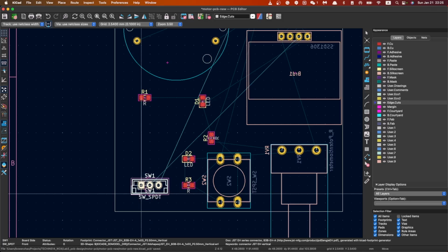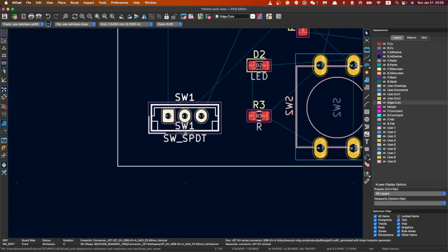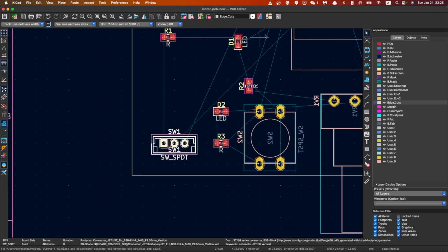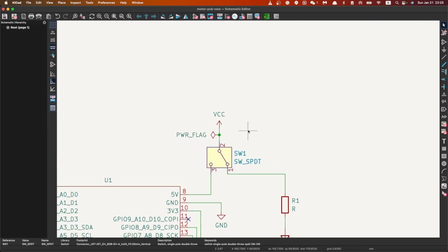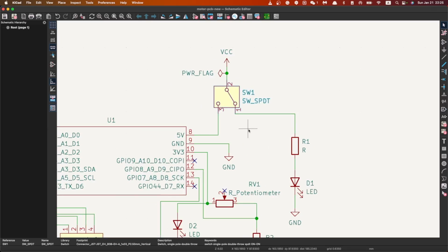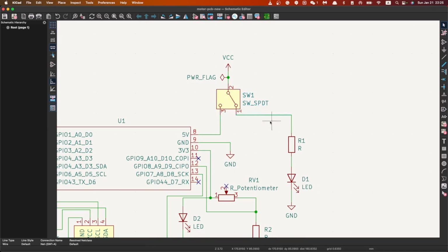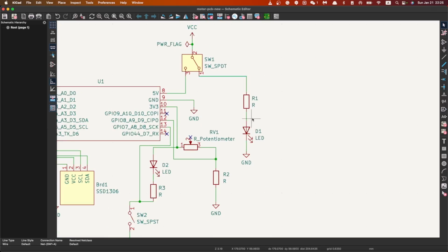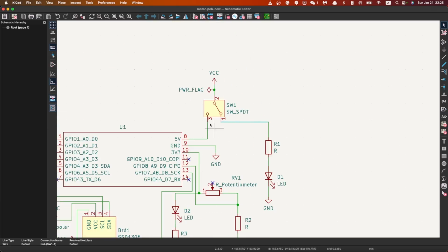Not so sure. Why are all ends of it being used? This is weird. So I found something wrong with it, which is that the LED is lighting up when the MCU is not being powered. So this is definitely not what we want. So I'm gonna use backspace to edit this line and create it like this to make sure that when the MCU is being powered, the LED will go up.